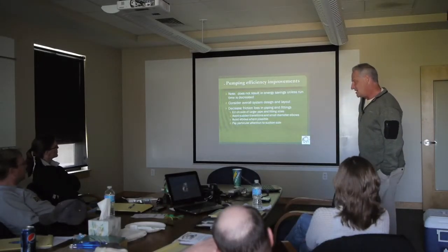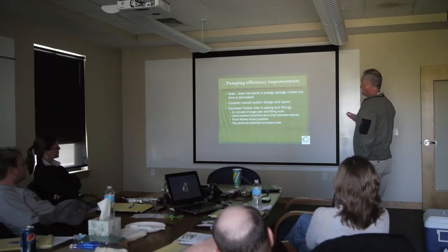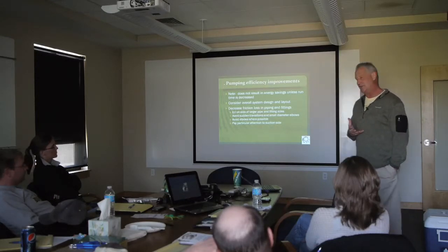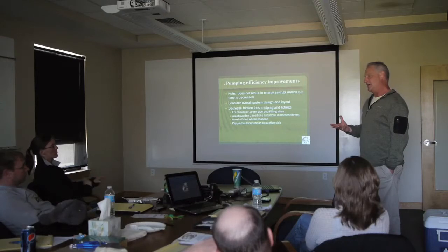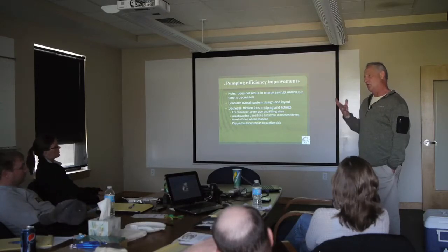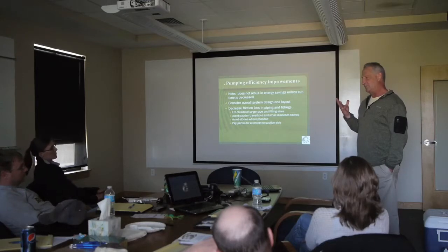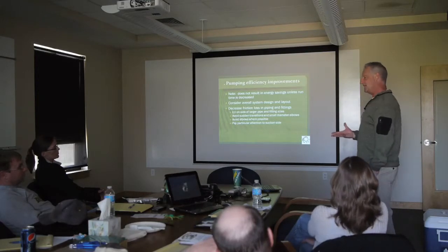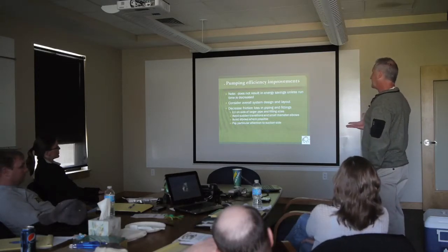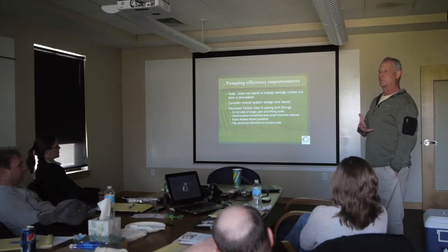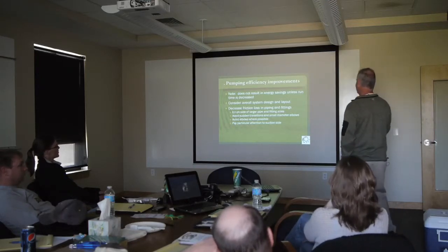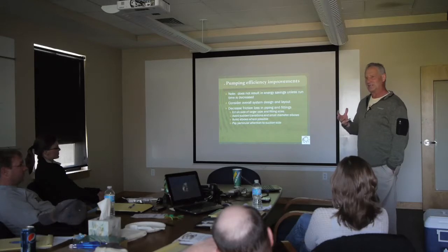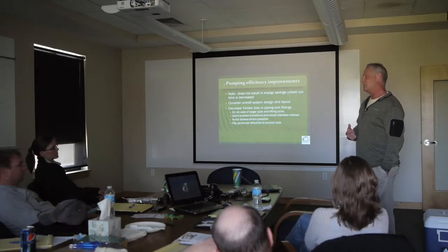Pumping efficiency improvements. Now, the whole idea is you're putting so much water on the field over some period of time. And so if you improve the efficiency, the whole idea is to pump less water. It only works if you run the pump less time or you put a smaller pump in. So you have to really remember that, at the end of the day, what you're really trying to do is run the pump less or put a smaller pump in.